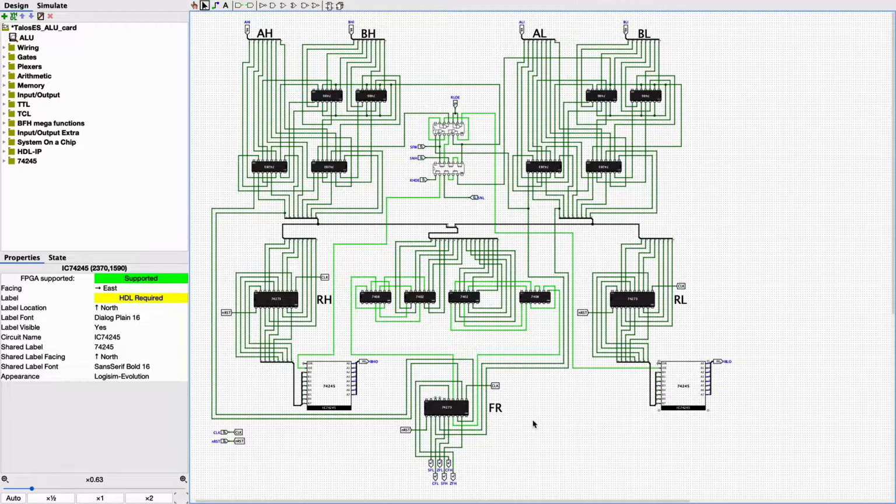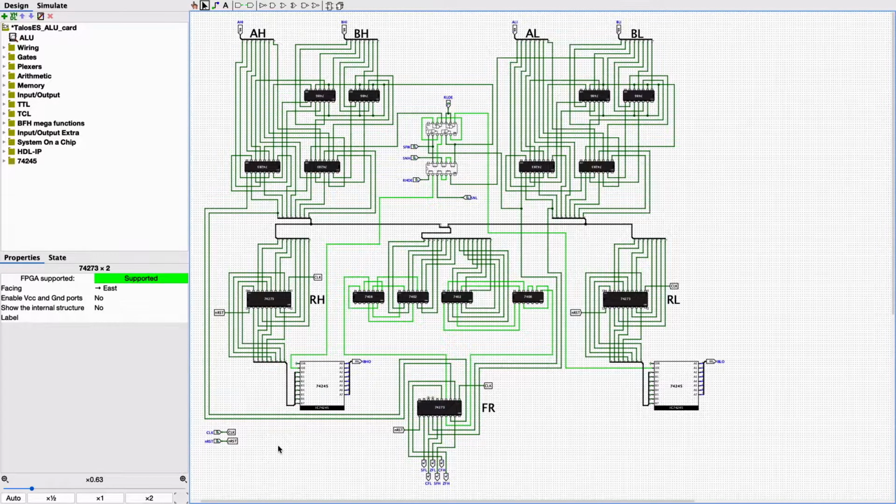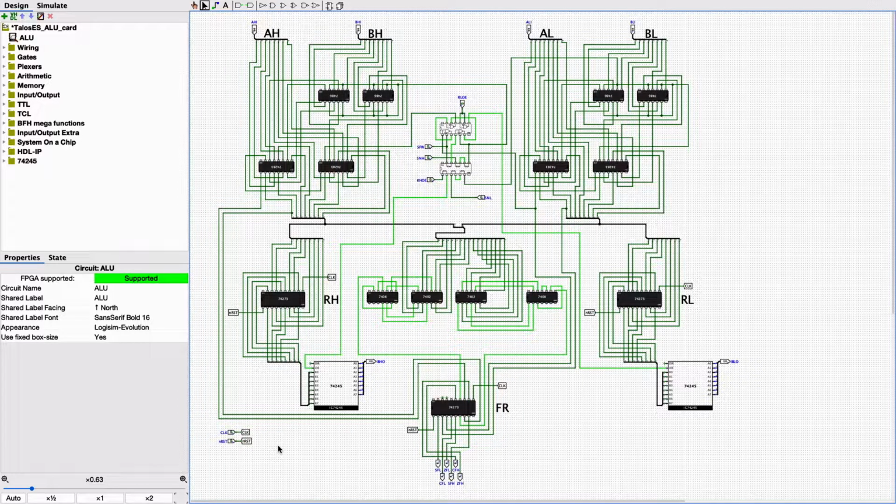I am tempted to say a little more about why the results of the ALU always go to fixed registers, the result register, as opposed to being directed to the register file, so you can choose into which register the result goes. Maybe it's not the time to say that yet, it may complicate things, but since I mentioned it, I will give you a very brief explanation, and more details are coming in future episodes.